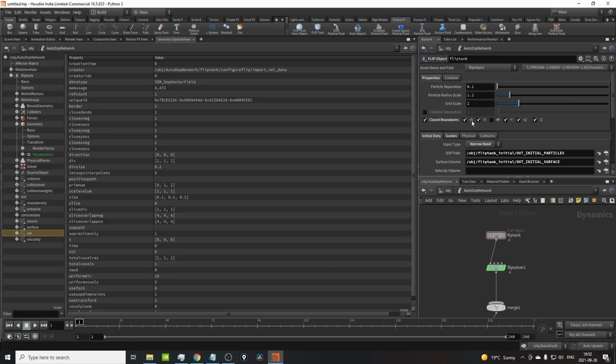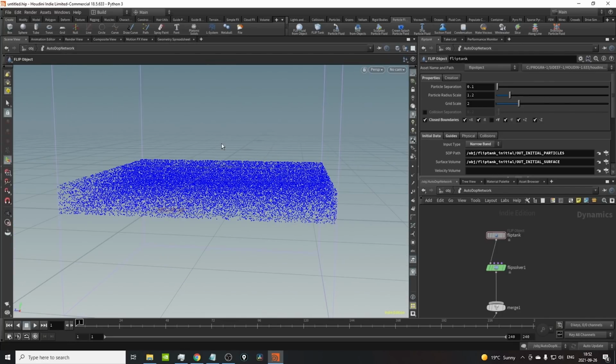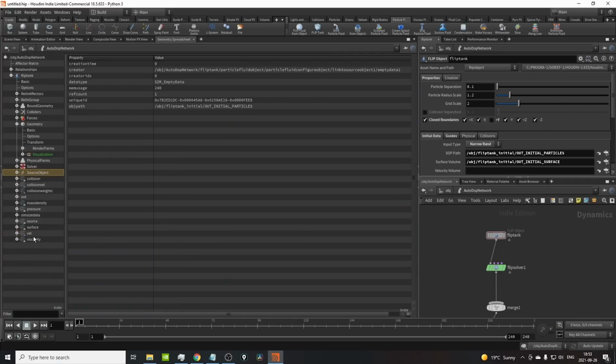Now, the reason this is important is because Houdini solves at a lower resolution than what you're actually simulating at. That is a very, very good thing in most cases, because you don't need as many voxels as you need particles in order to describe a really cool motion, right? You can have a really high resolution splash, but you don't have to have these super crazy high resolution volumes. And especially looking at this, we can see there's quite a few of these volumes.